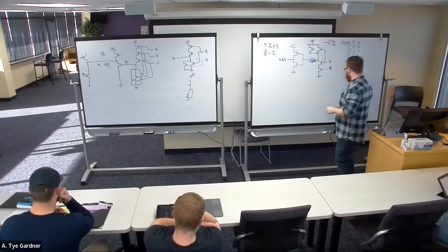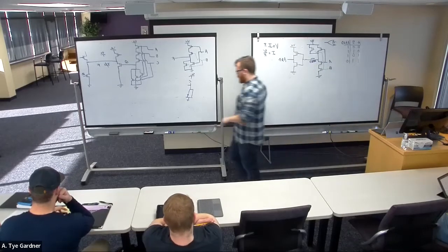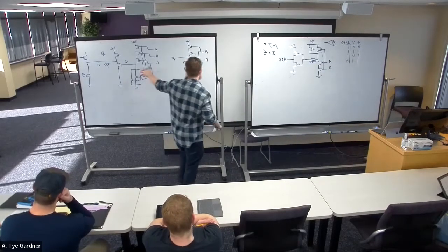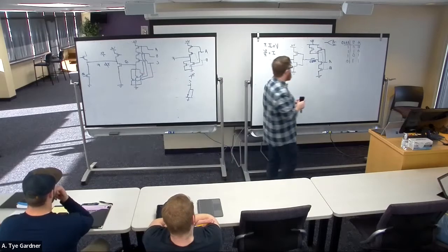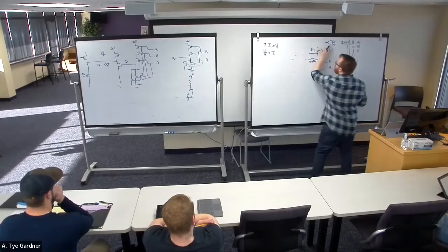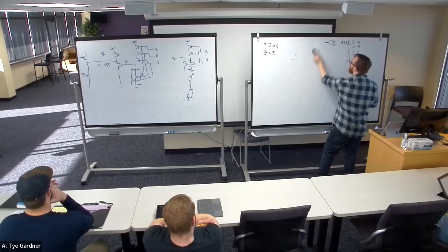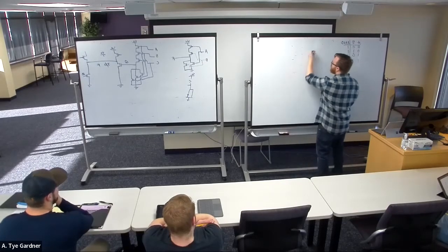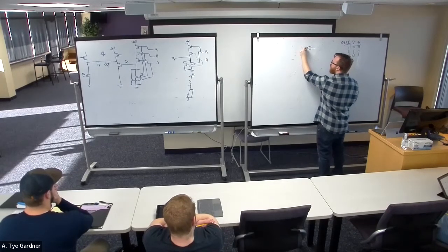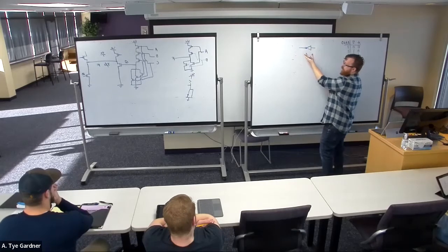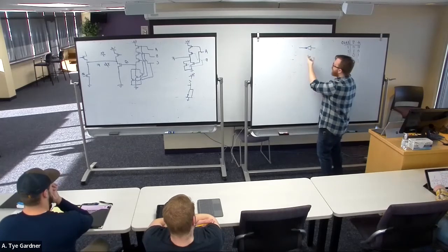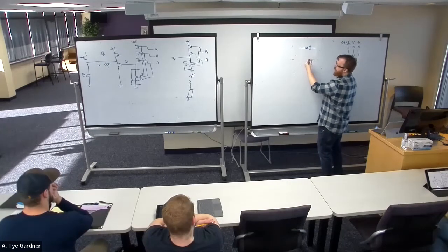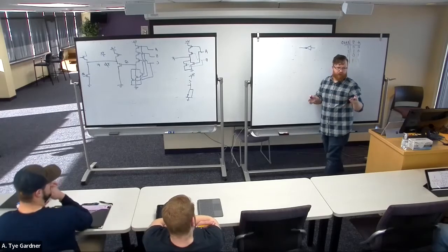When we use these devices, you're obviously not going to go draw transistors, right? That would be silly and weird. This is an inverter, right? We know how to build an inverter out of transistors. If I want to signal that my inverter has an open drain output,